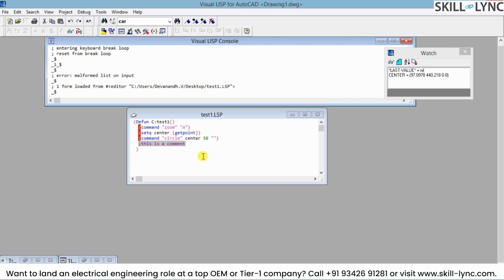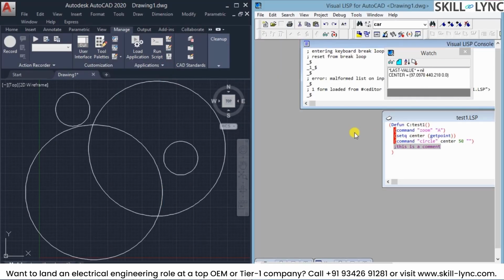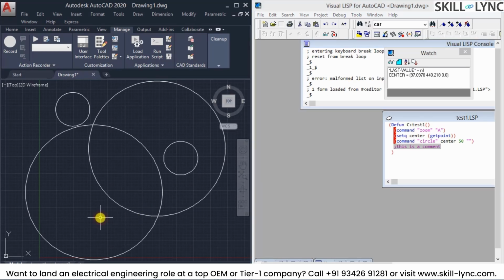So this is where Visual LISP is a value addition to your Lisp programming, because you can keep on building small modules, test them right away in your AutoDesk environment here, and then once you are done with it, you can save it as a whole, and next you can directly use this AppLoad functionality that you have here to call those functions one by one. Then also, as said earlier, using the startup menu, you can configure which Lisp functions you are using over and over again, so that you can configure it totally.